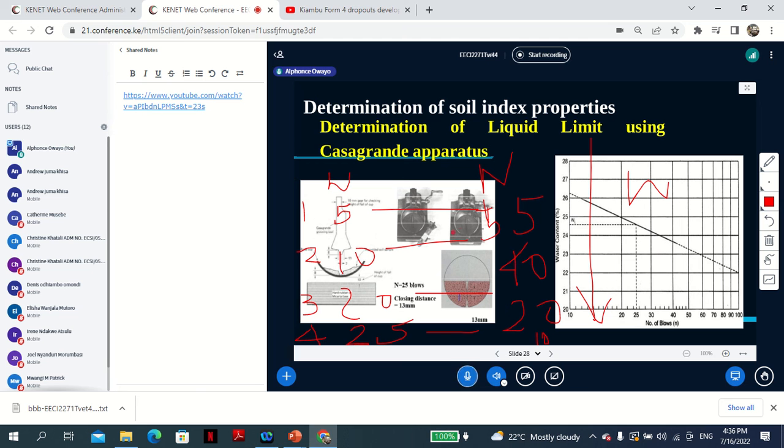Now, if you start with one and you don't know where the plastic limit is and you are reducing, you are lost already. You are lost because you don't know. But at least with the highest water content, all you know is the plastic limit has to have water content less than what you have. You know that's the highest, but the water content has to be below that. We don't know how much, but the behavior of the soil will tell you. But if you use any intermediate, then you'll be lost for those reasons.